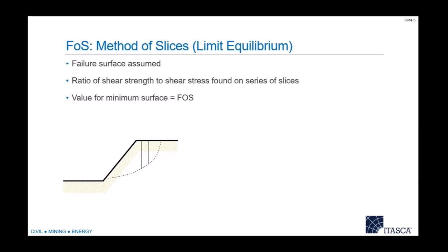Probably most of you are familiar with limit equilibrium. I'm sure you all did this in university. Probably all own a copy of Slide or GeoSlope or something like that. I'm sure you know how it works better than I do, where it takes the slices and does load balancing and so on. Figures out the surface, which produces the minimum factor of safety.